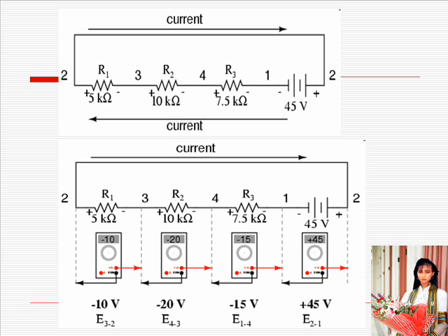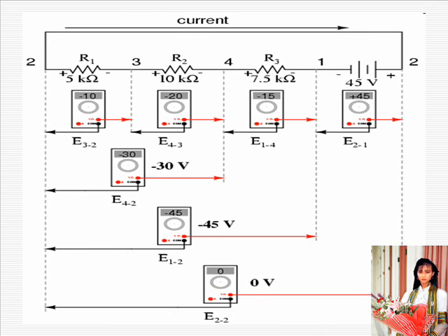Here we see what a digital voltmeter would indicate across each component in this circuit. Black lead on the left and red lead on the right, as laid out in horizontal fashion. If we were to take that same voltmeter and read voltage across combinations of components, starting with only R1 on the left and progressing across the whole string of components, we will see how the voltages add algebraically to zero.